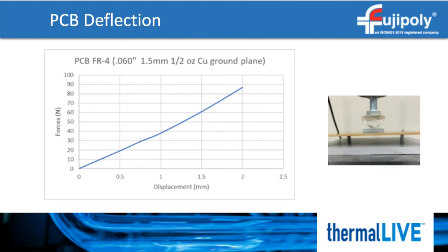Well, it's not something we could definitely say is okay, but we want to understand how the deflection characteristics of the PCB react to a gap filler. When we are working with a thermal gap filler, the idea is to compress the gap pad, not the PCB, but in some cases, or at least in the case of this PCB, it's totally unavoidable.